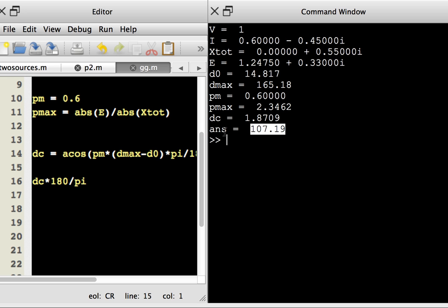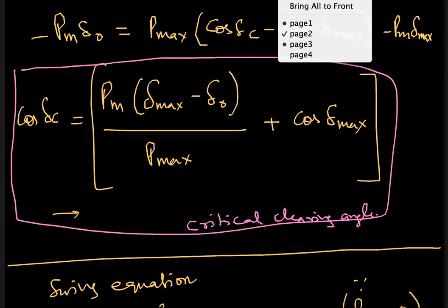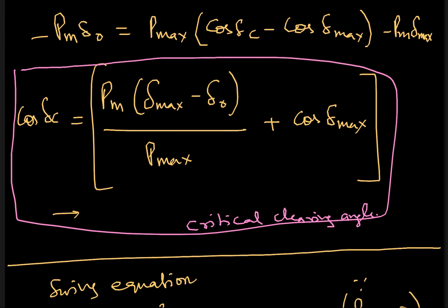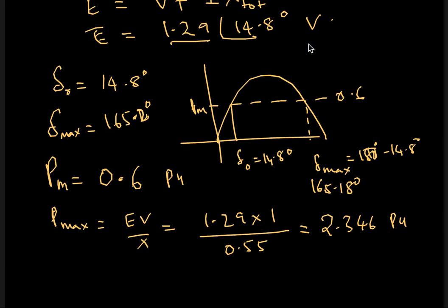Let me write it down in my diagram. As long as I clear the fault before 107 degrees, the machine will be stable; otherwise it will not be stable.